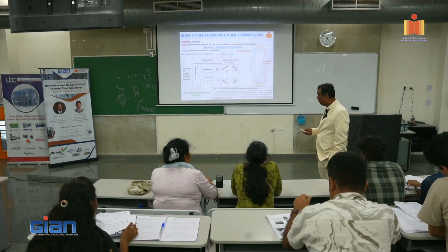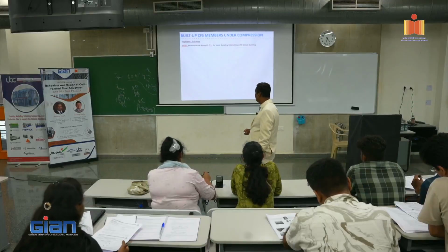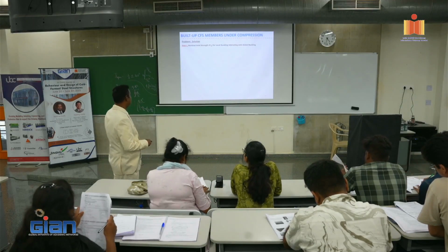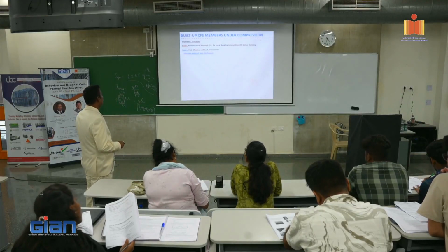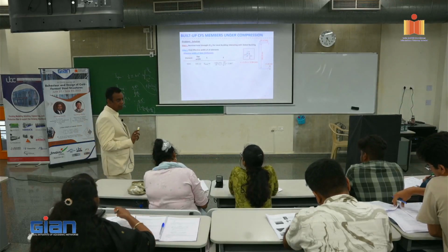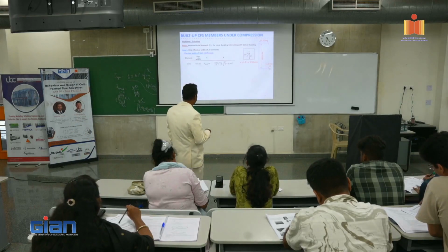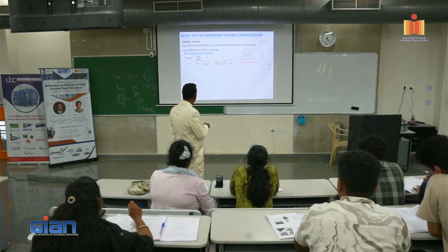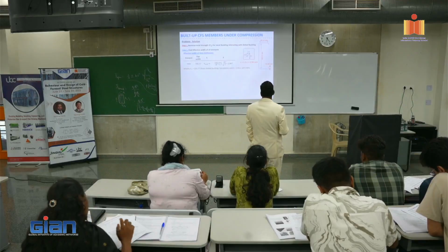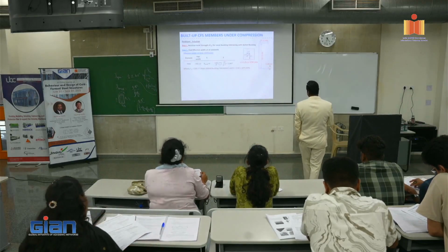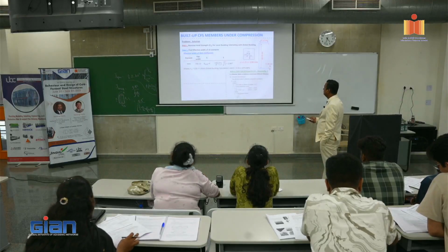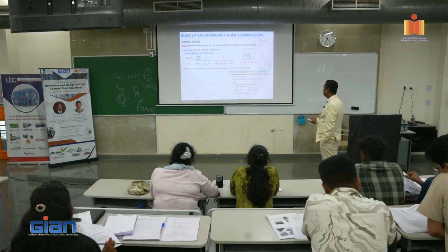Now, our objective is to calculate k. k is very simple. For a stiffened web, k equal to 4. We know that for all four sides simply supported, k equal to 4. So we put k equal to 4. What do we get here? We get 1.847. We know Fn equal to 259.77, E is this, and when we run the numbers, we can find out lambda.